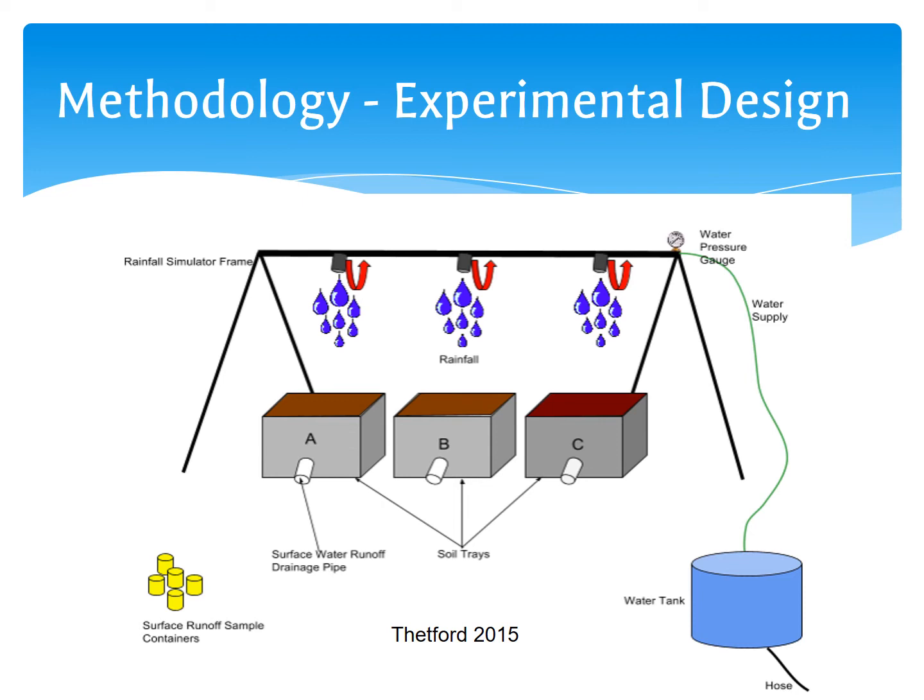Although the rainfall intensity was kept constant, the rainfall frequency was controlled by determining the time nozzles would rest after completing a single rainfall sequence across the soil profile. The rainfall frequency was altered to pause for intervals of either 10 or 3 seconds after a rainfall event had occurred between each experiment. Soil runoff was collected by catching the runoff from the soil profile with pre-weighed beakers.